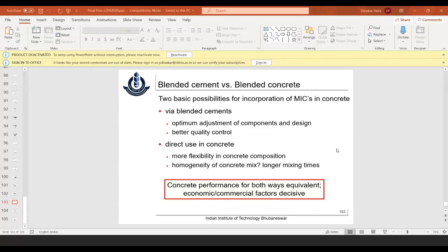As of now, nowadays, what we have seen, it depends on what element you're in. Suppose it's a slab element, go as per the Indian specification. That's it. Because nowadays with blended cements, if you want to cure it for another 3 or 4 days, it's good. If you don't want to reuse the formwork and you have ample time, you can cure it for another 3 or 4 days. Actually, that's not at all a concern. But my suggestion is, go as per the specifications.